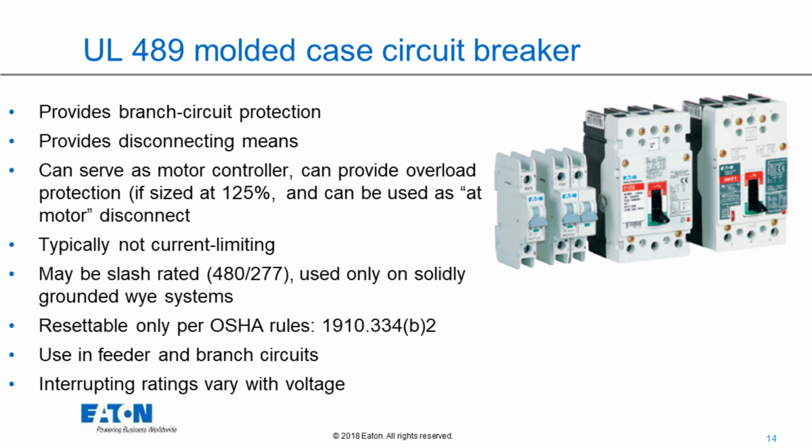And the actual device itself, like if it's a breaker, has to be evaluated to see if it's still appropriate for use before it can be reset. So if it's a short, a lot of things have to be done to investigate to make sure that resetting that breaker or reinstalling fuses is going to be safe.